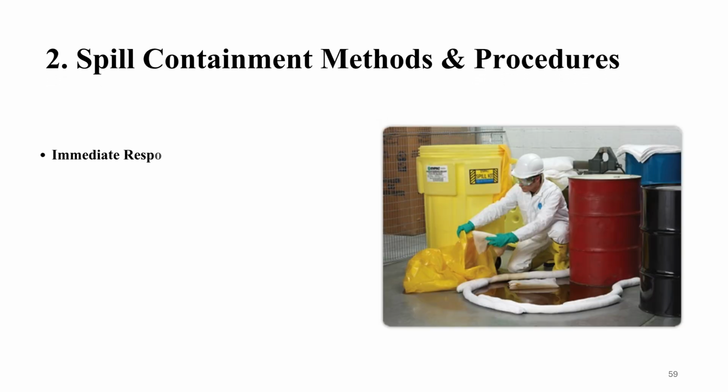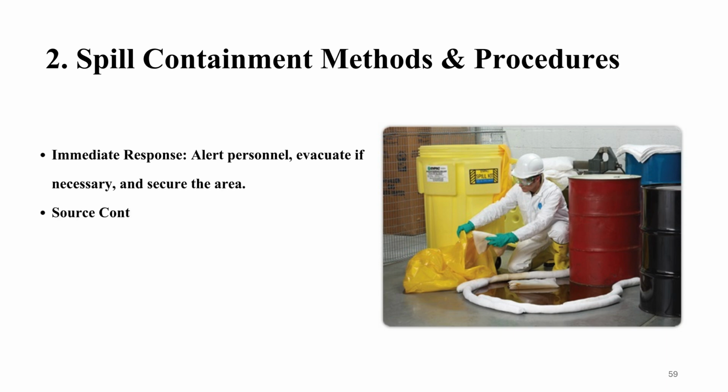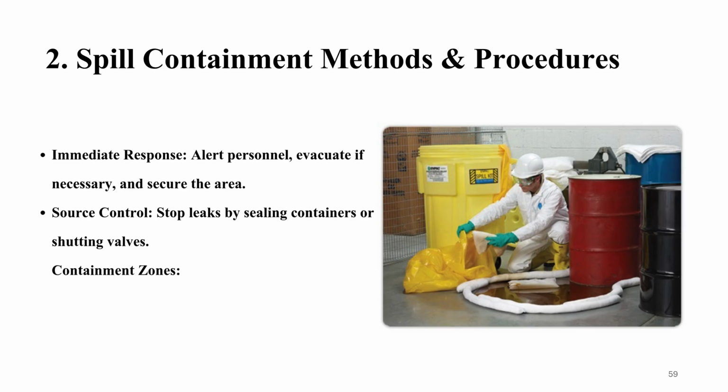2. Spill containment methods and procedures. Immediate response: alert personnel, evacuate if necessary, and secure the area. Source control: stop leaks by sealing containers or shutting valves. Containment zones: prevent spread using barriers and containment strategies.